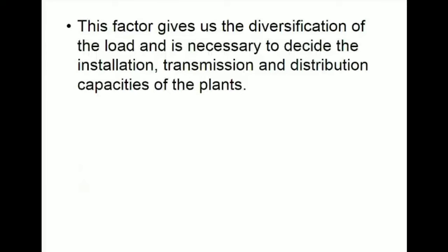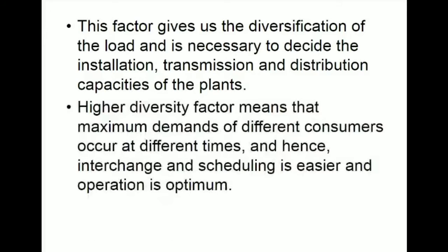This factor gives us the diversification of the load and is necessary to decide the installation, transmission and distribution capacities of the plant. Higher diversity factor means that maximum demand of different consumers occur at different times, and hence interchange and scheduling is easier and operation is optimum.